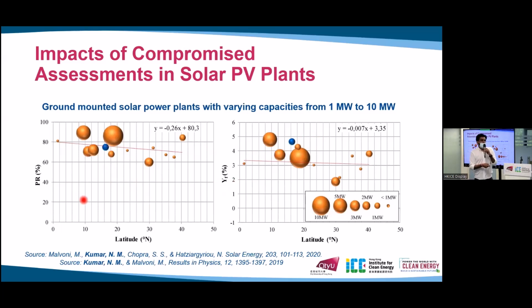Now, what are these factors? Mostly in science research, we only see either VOC or ISC or Pmax, or at last, the energy density and fill factors. But when we take these PV modules into real time, these factors are just considered benchmark data, standard testing conditions data. Those data will completely differ from the actual performing conditions. That's the reason the research community has come up with a concept called PR, the performance ratio.